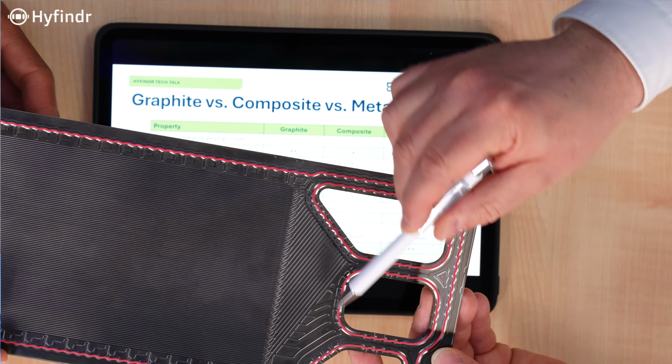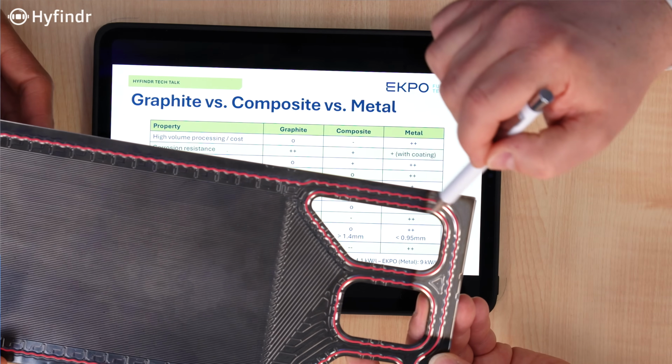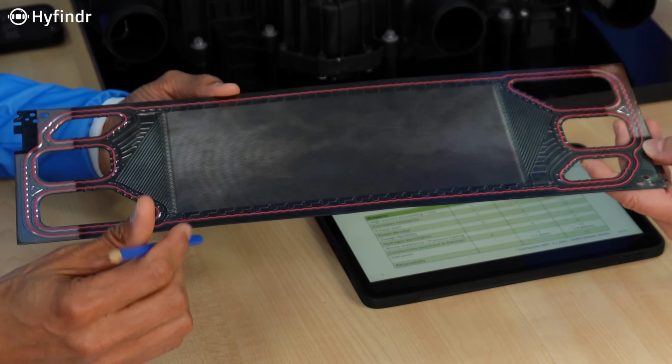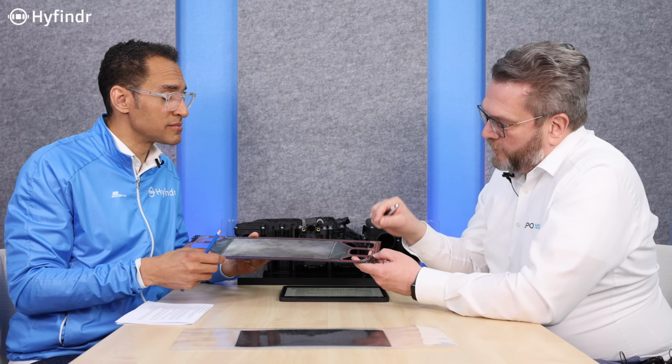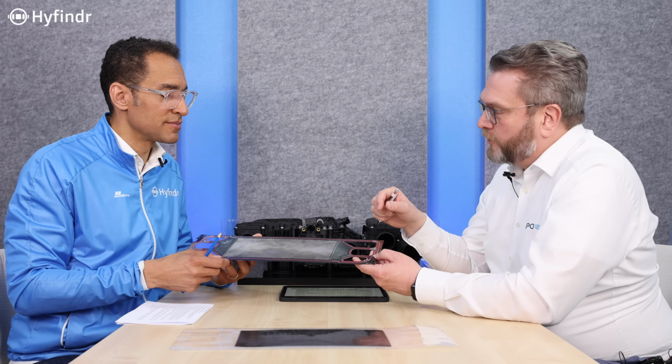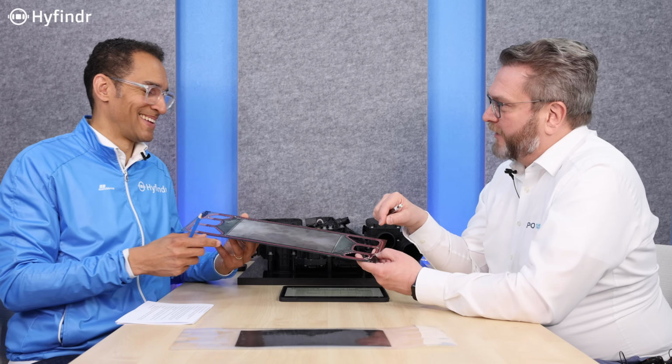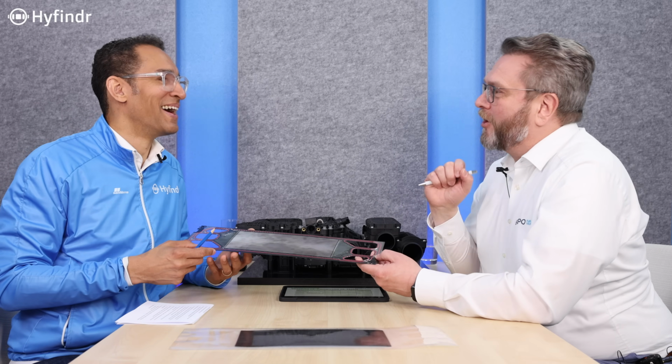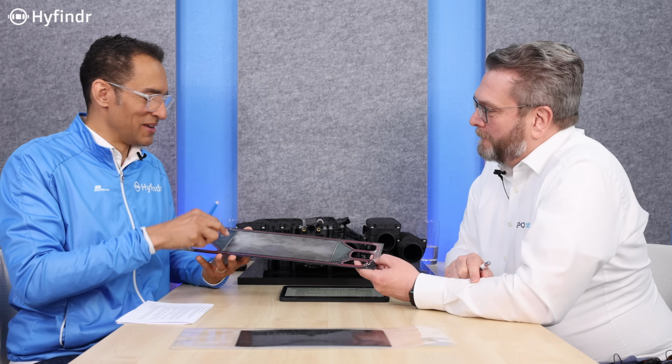Yeah. So also if you control the chemistry of the seal, for example, as you can see this in pink, this is a thin rubber layer on top of a metal seal. And if you control this chemistry, because this is all designed by us, you can reduce the impact to the metal. So if you just go to Home Depot and take some silicone from there, you definitely will fail. So even a good bipolar plate will then discolor. Okay. So that is key to managing the corrosion topic, the coating, right? And how you seal and how you manage the whole stack. And also operation time.